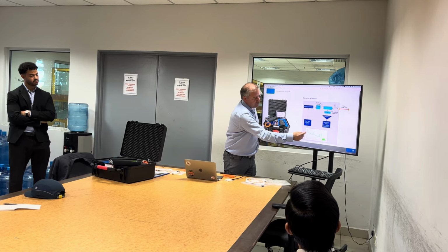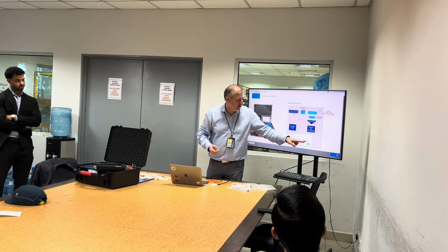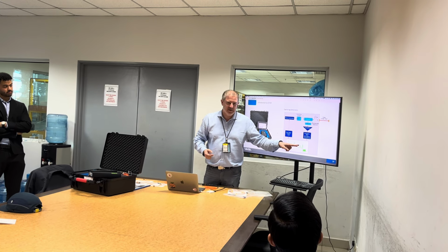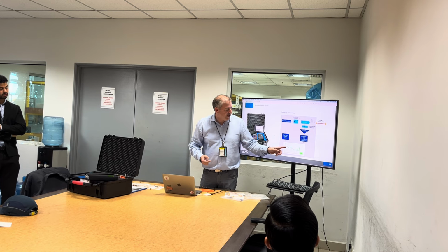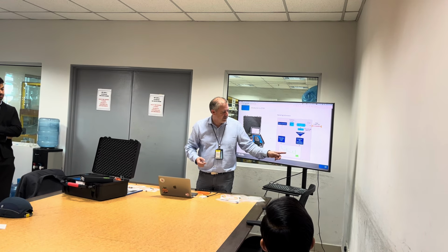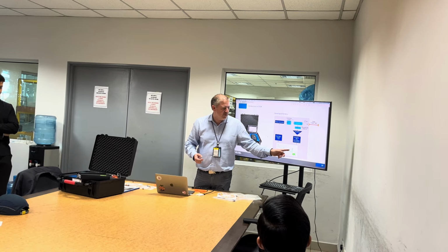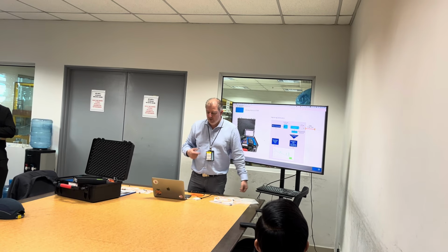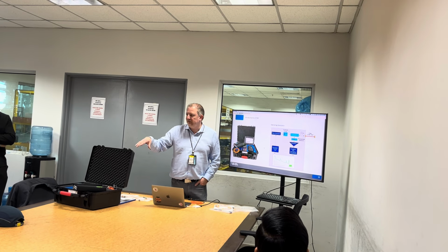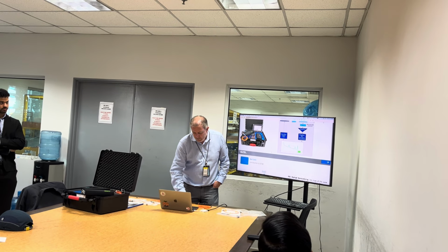And then at the end we can process a graph like this, and this is what we are gonna analyze. So a typical shape would be like a small fault like this, or a reflectance like here, possibly a connector, a bending radius, connector, and a fiber. We'll review that, and the system will help you also to figure out what type of fault you have.